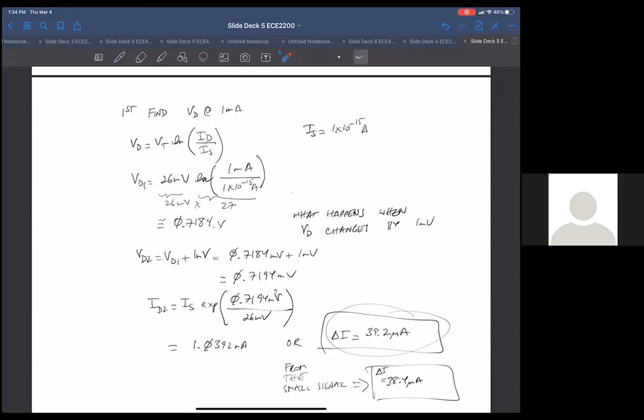It's going to take you a while longer to do it. I did a natural log and exponential, neither one of which would you be able to do in your head. So you'd have to calculate each one. And again, just think about, this is a single diode we're looking at. Imagine multiplying the complexity of using the full model versus the small signal model if you have a large circuit. It's a huge difference in complexity.